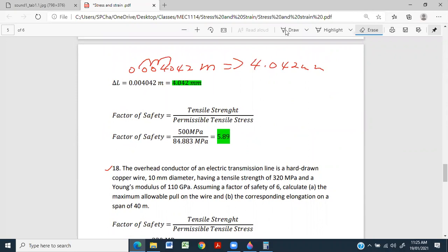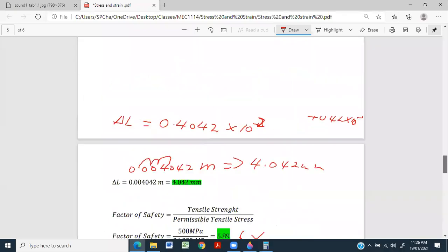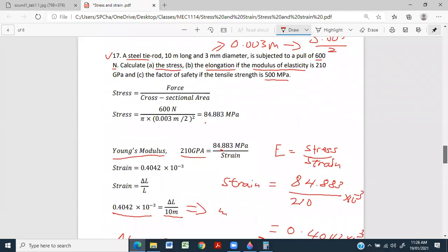And we see the safety factor is 6, which is good. Well, almost 6, which is good. That means it's very far from its limit, right? Safety factor is 6, 6 times away from its limit. It's not very close to this 500 megapascal limit. If we were to apply more stress and it reached that, then the steel bar would break, right? So we're at a safety factor of 6, which is good, and this system isn't nearing breakdown or at an area where it would collapse or anything like that.